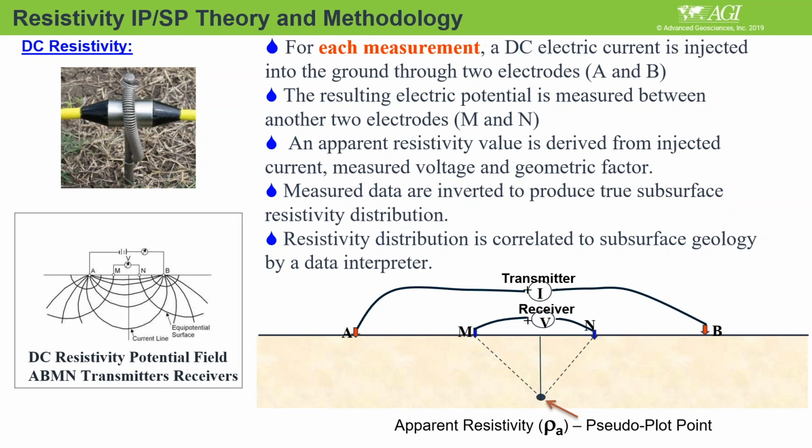As you know, let me pick up my laser pointer over here. Okay, everything is based on two current injections, A and B, what you can see here. So you need to inject current between two points, positive and negative, and then that current line goes from A to B, for example, like this. And then it goes deeper and deeper.